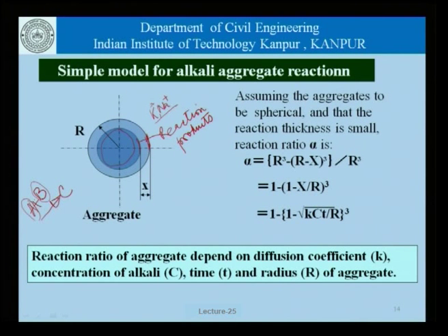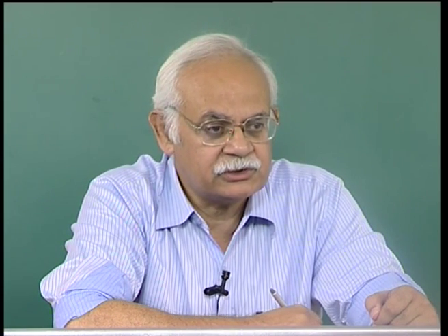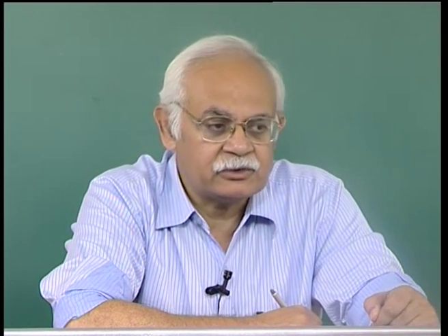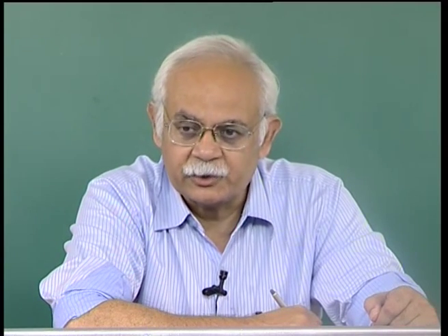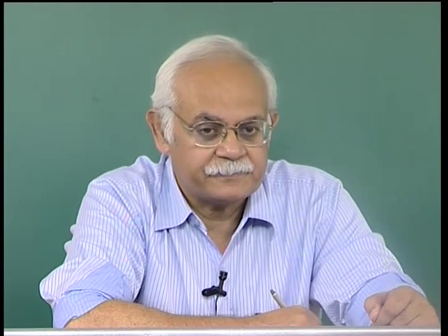So, in the scenario like that of alkali aggregate reaction, the situation translates to, do we run out of reactive minerals in the aggregate? The answer is pretty much no, because there are enough aggregates and therefore enough reactive minerals within the concrete for the reaction to go on. Do we run out of alkali metals in the pore solution? The answer could be yes or no, depending on the amount of alkali present in the pore solution to begin with, and that is related to the amount of alkali present in the cement and the quantity of cement in the concrete.